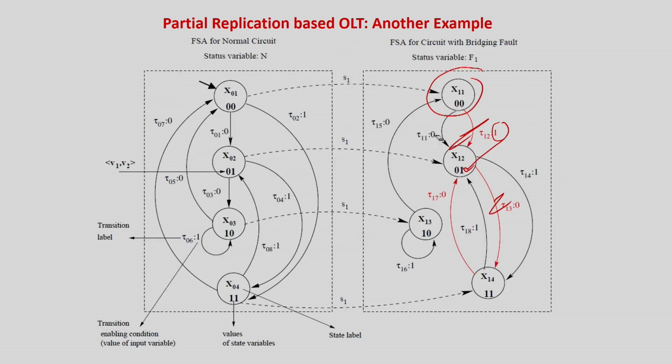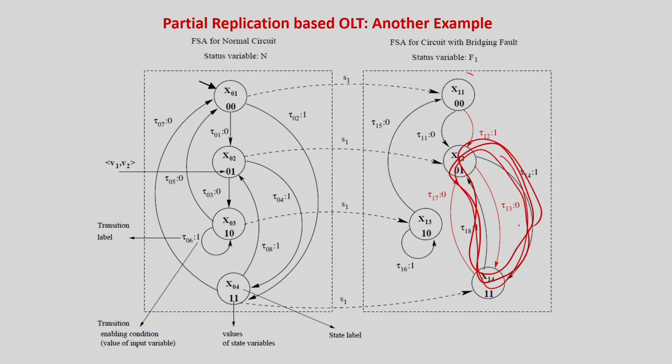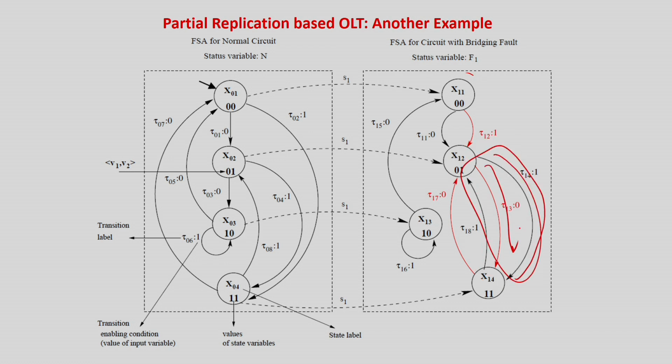because I have no control on the operation of this finite state machine. It can go over here, it can go over here. I have no control because the inputs are coming from the environment and the circuit is traversing these FSMs. So it may come here, it may go here, it is totally traversing over this. I have no control. But sometimes, maybe after so many times, once it takes this path, and for the idea of trading off the area of the tester, you have dropped this FD transition. You have not considered this FD transition in the detector design. So what can happen? It will revolve over here, then this one is happening. The error has occurred, and this is what shows a difference from the normal behavior.